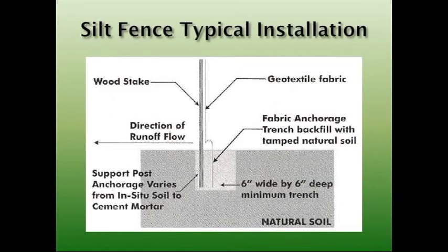This is a good diagram for the silt fence. I think it's in that Missouri handout we gave you about silt fences. A lot of times you can put a trench right here if you need some extra capacity. Just make sure you compact this in, but you can put a trench right in here to catch a little bit more. Sometimes, if you don't want to maintain it as much, you can put a trench right there to catch it. Keep that in mind.